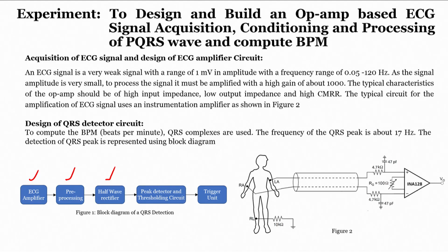So, one step is our rectification, where using diodes we will convert our AC signal into pulsating DC, right. The problem with a simple diode is impedance matching. So, if you want some gain as well as impedance matching, rather than having a simple diode, if we go with a diode with an operational amplifier, it will always have a better advantage.